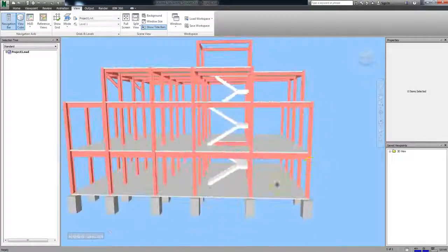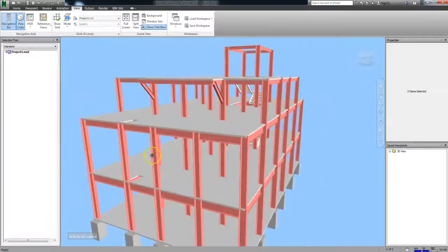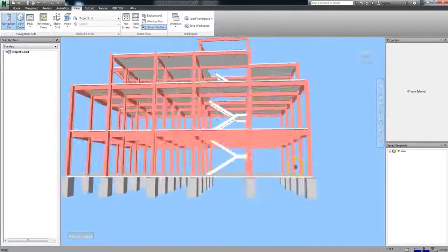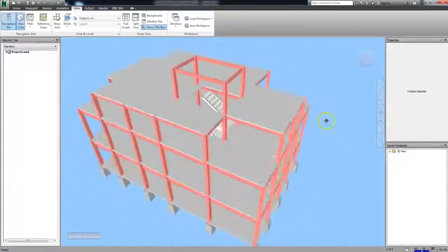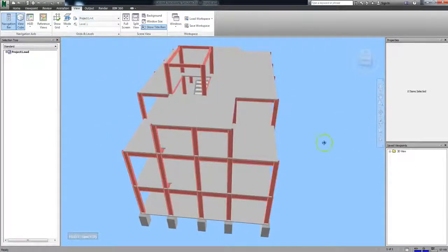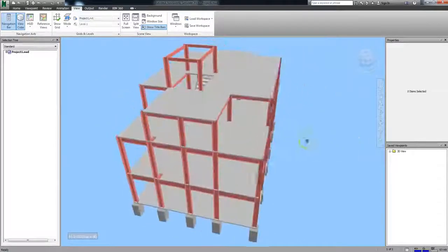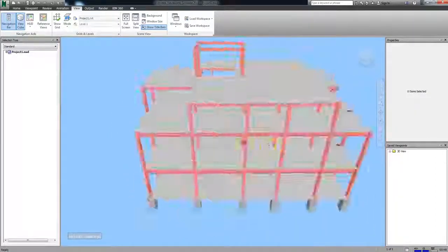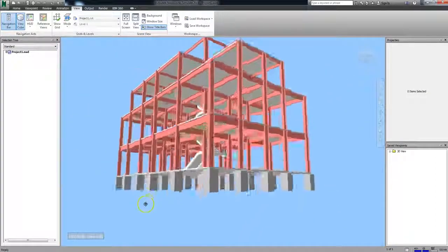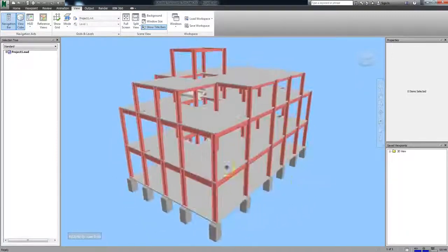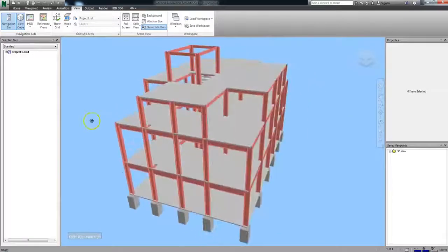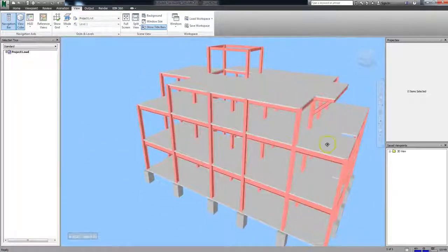As you can see, we have free range of motion around the pivot point in our model. All you have to do is hold the left mouse button down and shift it around to move around the model. You'll notice though that the model always maintains a general up direction, and it's fairly easy to get back to the view you started with. You can think of it as moving the camera around the model, while the model itself stays stationary.